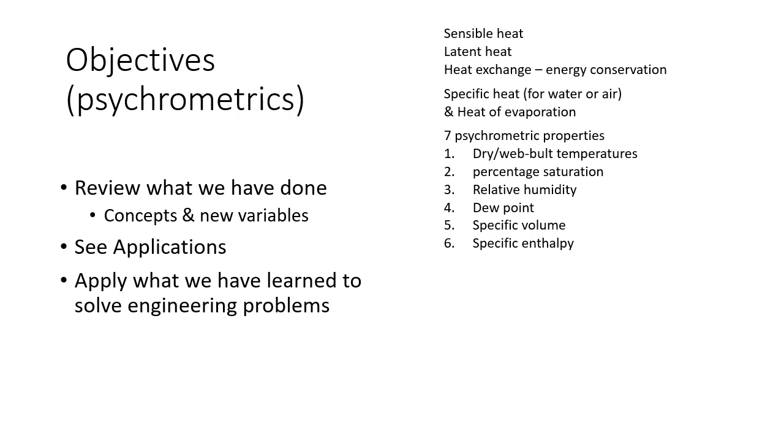Right, based on these three concepts, we looked at 7 psychrometric properties of the air. Right, we start from water and we go into air. We consider air is a mixture of vapor and dry air. So therefore, we need 2 variables to define the state of the air. The most common way is to provide dry bulb and wet bulb temperatures. These 2 are easily measured by sling thermometers.